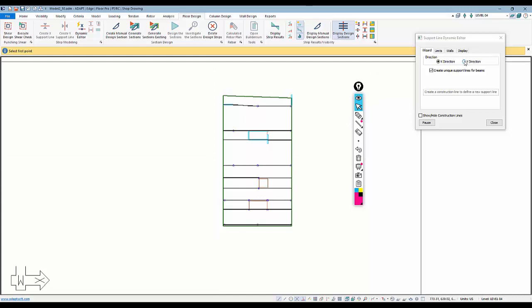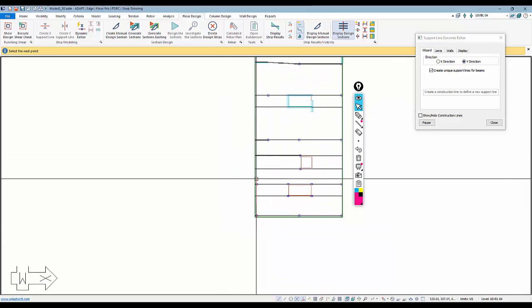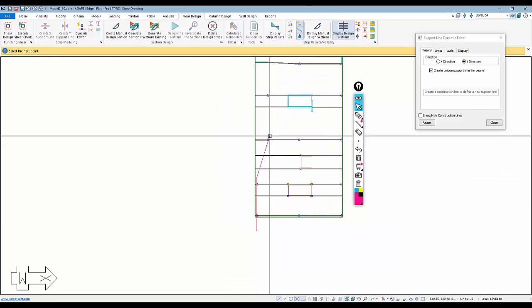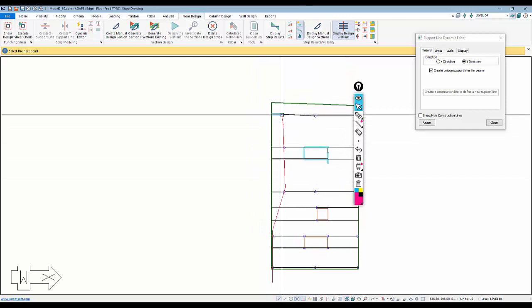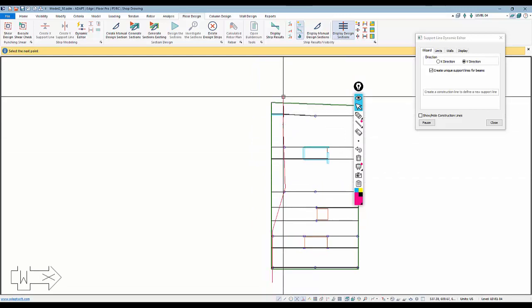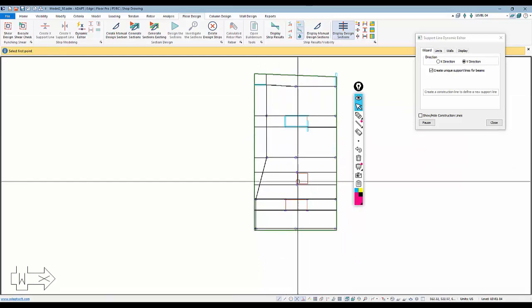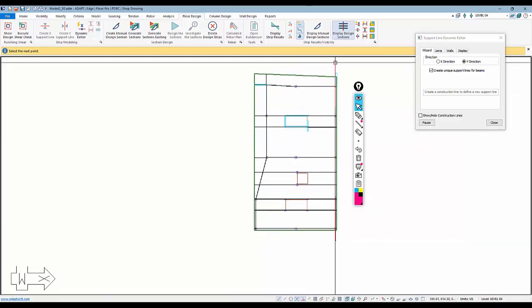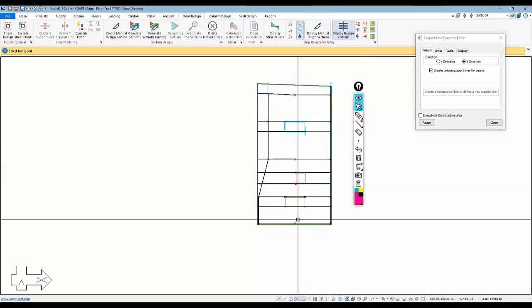I'm now going to switch this to the Y direction, and we'll do this direction. I'll pass through these first two columns. I'll swerve over to hit that column, up to hit this column, and then I want to click at the endpoint of that wall and then vertically, and that picks all those points as support points for that support line. I'm going to flip over to this other side here on the right edge. Okay, and that's the support line there.